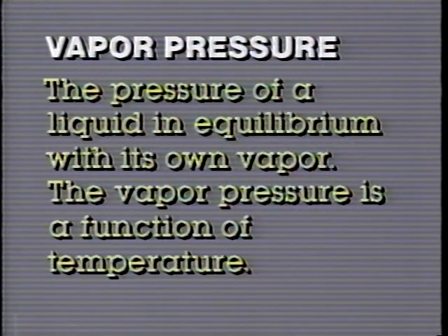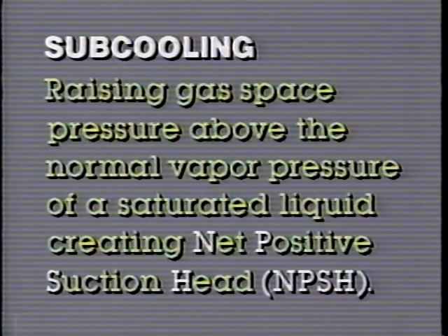Vapor pressure, the pressure of a liquid in equilibrium with its own vapor. The vapor pressure is a function of temperature. Subcooling, raising gas space pressure above the normal vapor pressure of a saturated liquid, creating net positive suction head, NPSH.